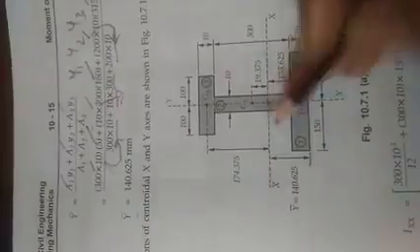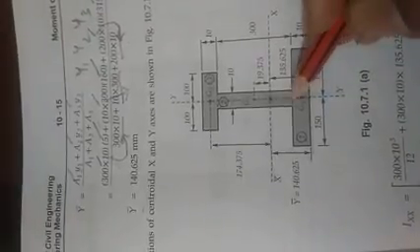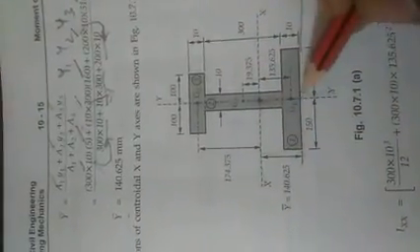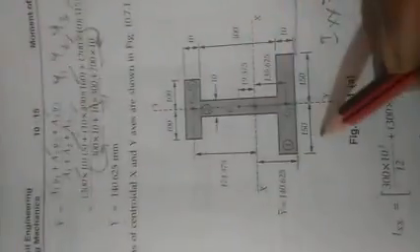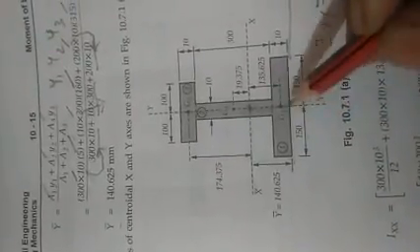But from here to here, what height will you get? That height will be determined by using this. So from here to here it will go like this, and exactly at 140.625 you will get the centroid, that is y bar. See here, how you got this line: the total length is 300, divided by 2 is 150. If you cut exactly here and fold it here, the centroid will lie on this line.